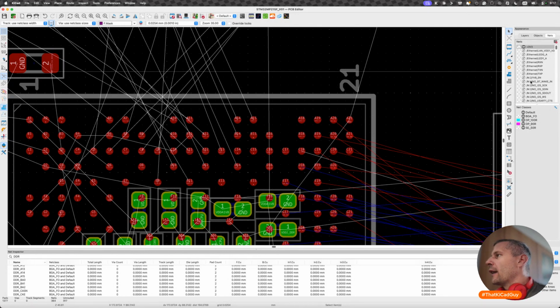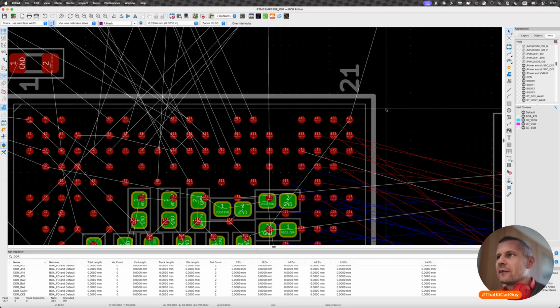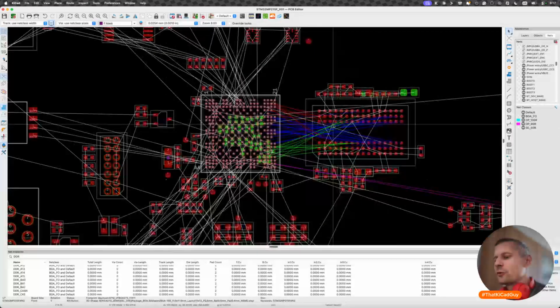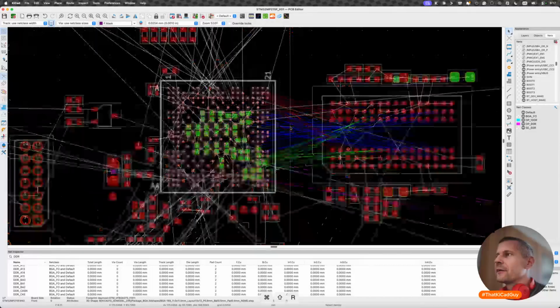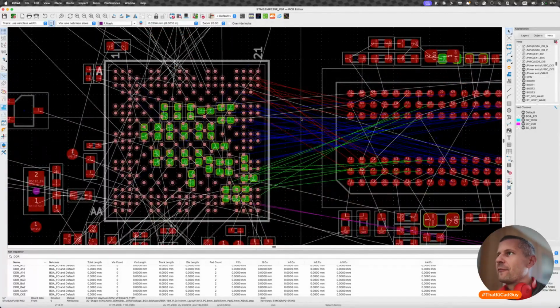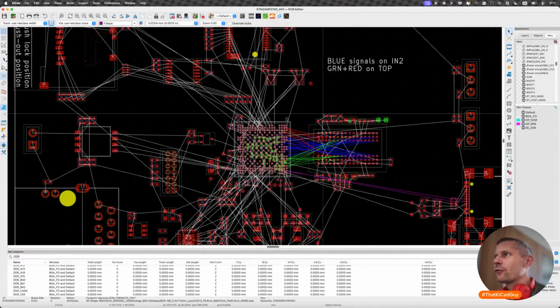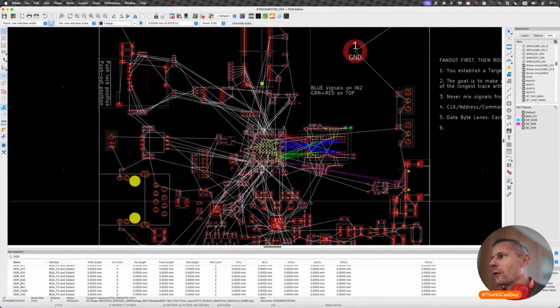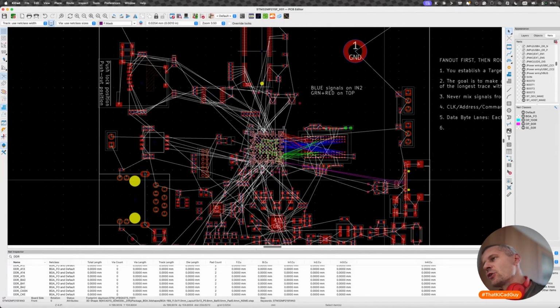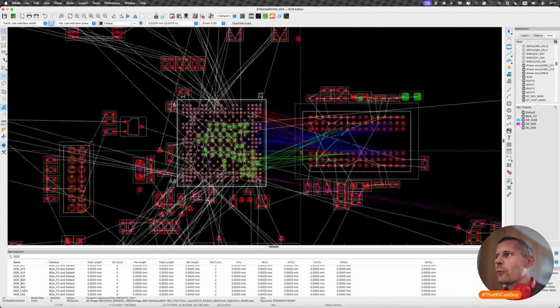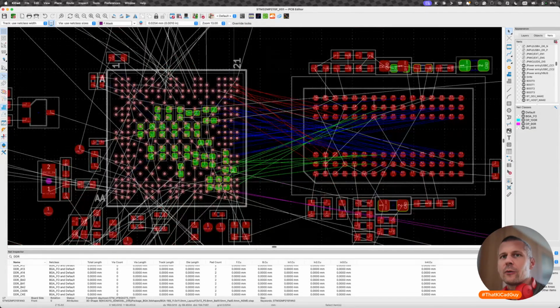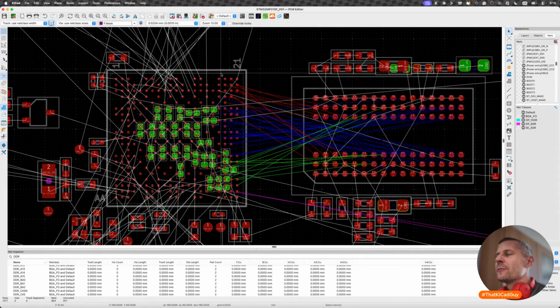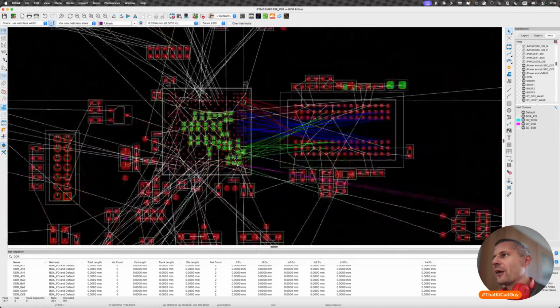And additionally, I disabled visibility of some signals because I want to use the red ones here. Last time we assigned colors to all the net classes, and I switched off the, let's say, normal white net classes coming through the DDR memory or through the group of our rainbow signals, because I want some clarity, some easy orientation, easy to navigate area.